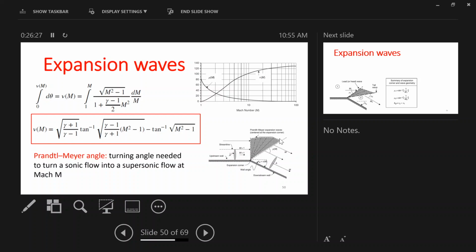So essentially, let's say you're solving a problem, you have an expansion angle. Keep in mind that the angle we were working on was before this. So we were talking about the nu of this, the Mach number of this part, right? We don't really care about that part. We really care about the downstream part. So if you use the Mach number here, or the Mach number you want to have here, you have to deal with the nu of the downstream Mach number, downstream flow. Does it make sense? Okay.